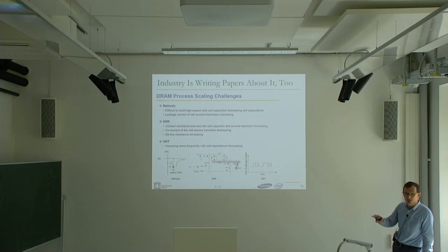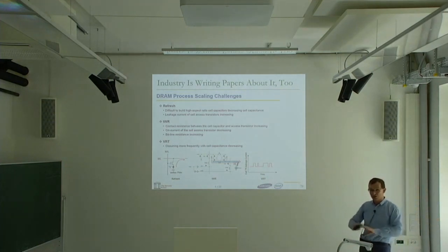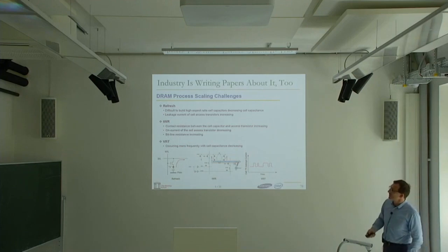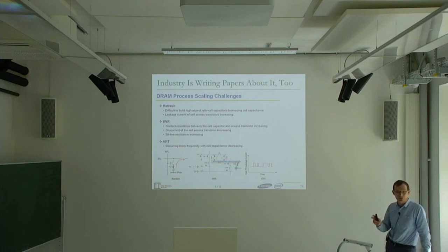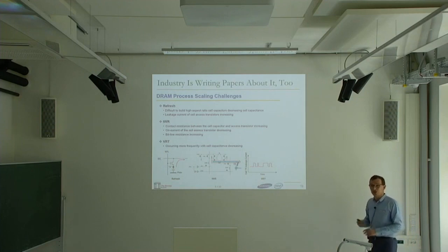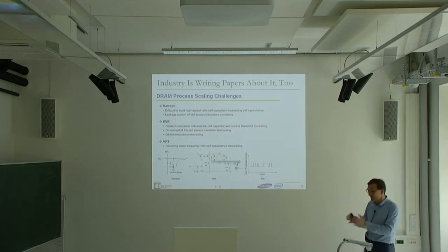Subarray level parallelism. They said that you should increase the parallelism inside a memory chip such that you can access subarrays independently so that you can tolerate these latencies better. One of the other solutions is actually employed today. They basically said we should put error correcting codes inside a memory chip so that we can handle some of these issues better. And today's low power DRAM chips have error correcting codes inside them, inside the chip basically.